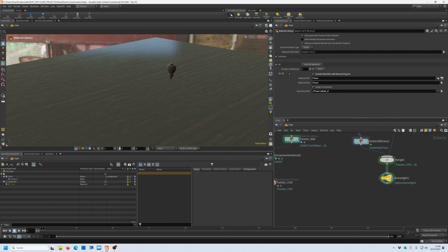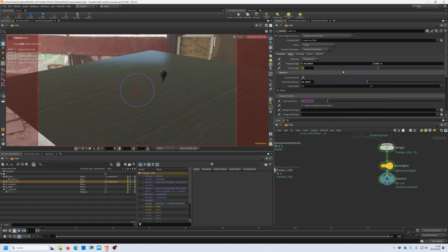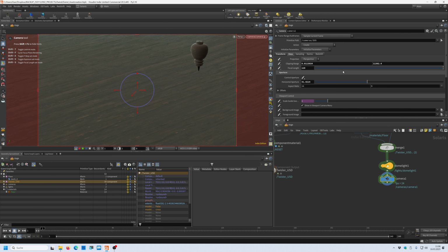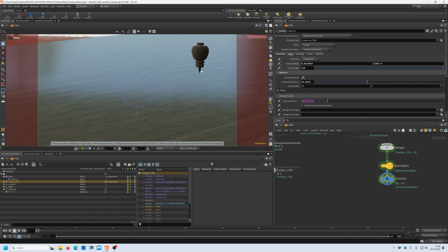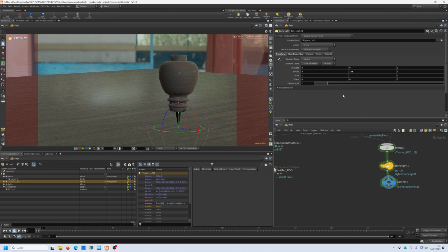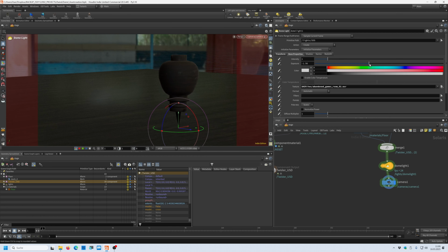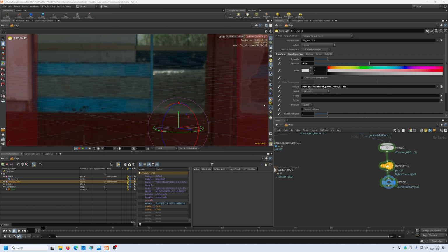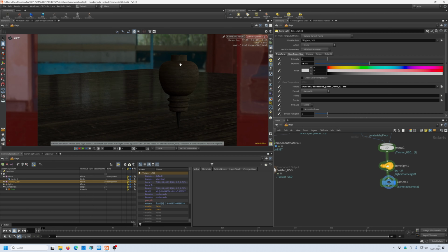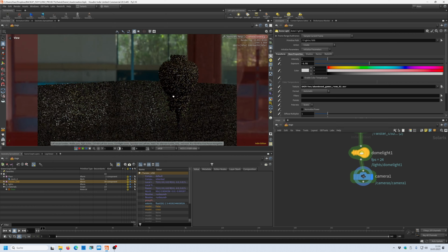All right, let's create a camera and make some changes. First of all, the view, the focal length, I like to have a 120 millimeter lens focal length, and I position the camera into my scene. And what I also do is in the base properties, I bring down the exposure. And now it's time to start the XPU render. And now we already see that we have our scene and we have our material applied. And now you can see that the scene comes to life.